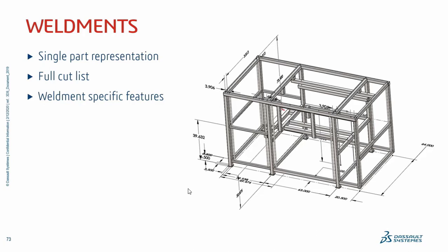So please don't make it an assembly, because that contributes different files and different mates, which is not needed. You will get the bill of material for this part inside the weldment too. So whenever the welding is happening in a single part, please use the Weldment command tab. It will give all the details required from the manufacturing point of view.